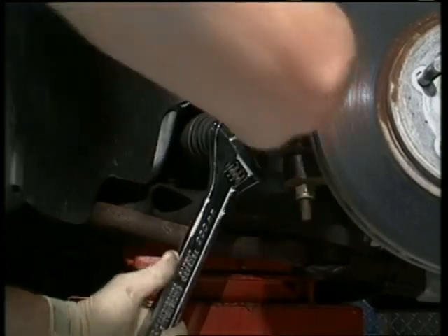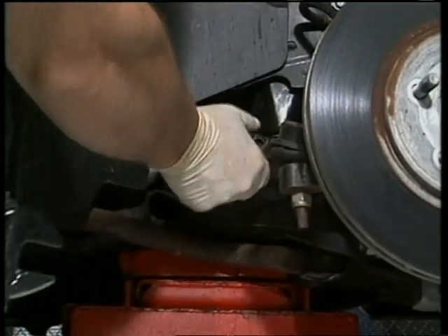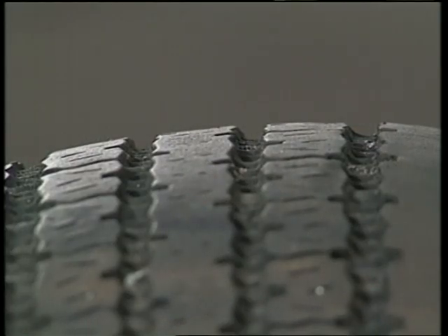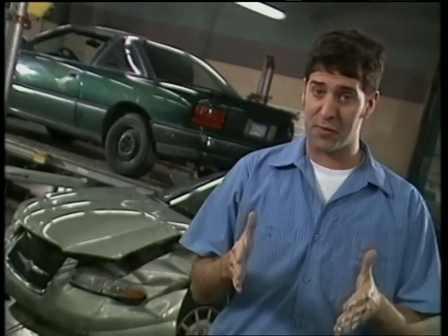Toe adjustment is critical to tire wear. If properly adjusted, toe makes the wheels roll in the same direction. If toe is out of spec, then one or all of the tires are being dragged sideways, causing rapid tire wear. Rear-wheel drive vehicles are often adjusted to have slight toe-in at the front wheels.